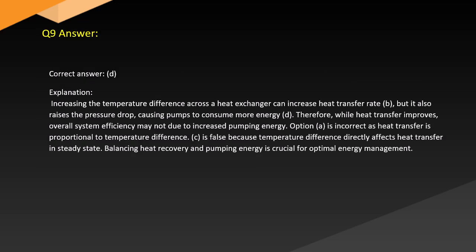Answer. Correct answer: D. Explanation. Increasing the temperature difference across a heat exchanger can increase heat transfer rate, B, but it also raises the pressure drop, causing pumps to consume more energy, D. Therefore, while heat transfer improves, overall system efficiency may not, due to increased pumping energy.